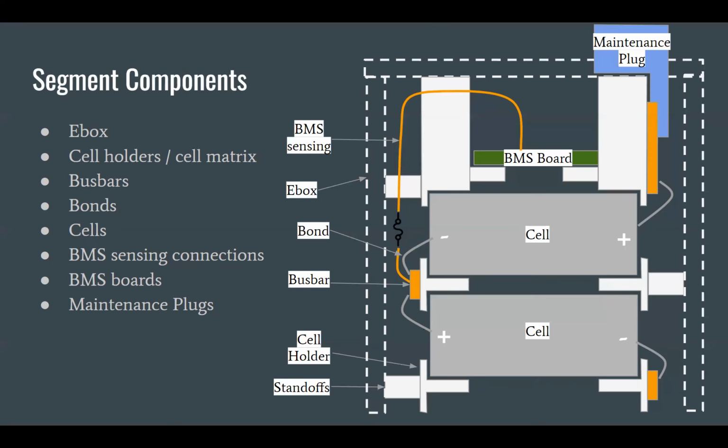That ended up being because of a confounding set of factors on bolt sizes and nut sizes, the materials that we had, and the bus bars that we used. Like, those ones. That's what I mean. There's a whole bunch of factors that went into why they're that tall. But in retrospect, having them this tall ends up wasting a moderate amount of airspace that, once you look across all 6 segments, ideally you wouldn't waste that extra 2 inches.